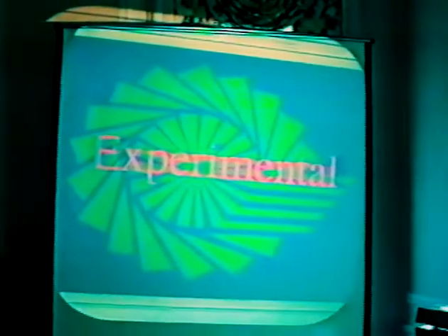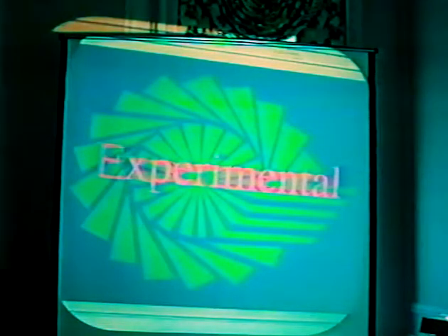We'll now go into our experimental section. Basically, our experimental plan was to look at NO adsorption under typical flue gas or combustion flue gas conditions, both in terms of gas concentrations and in terms of temperature. Now, when we started this project, there was a lot of information available in the literature on NO adsorption onto activated carbons, but we couldn't find anything dealing with that adsorption under conditions which you would find typical of a combustion flue gas stack. And so that was our plan when we set out.